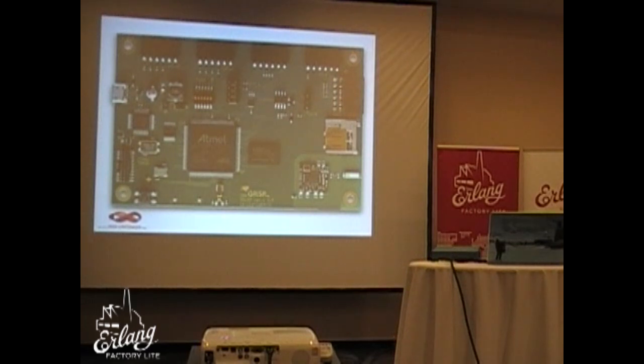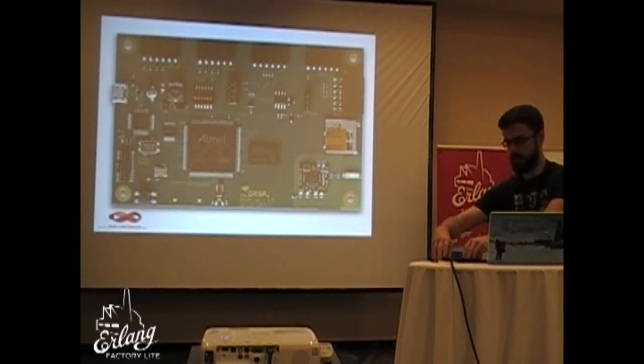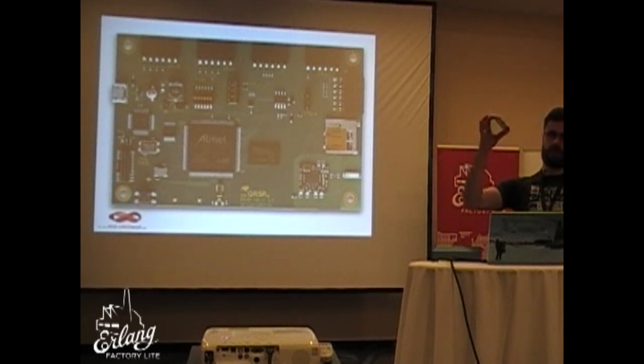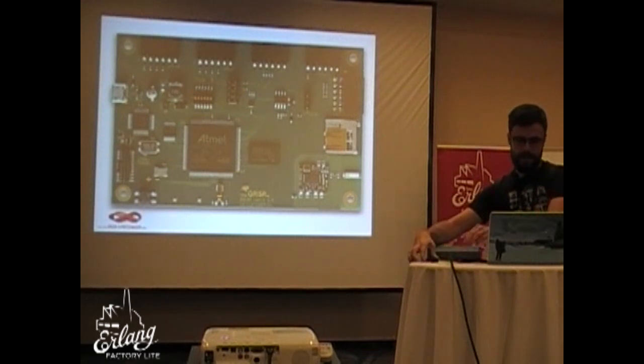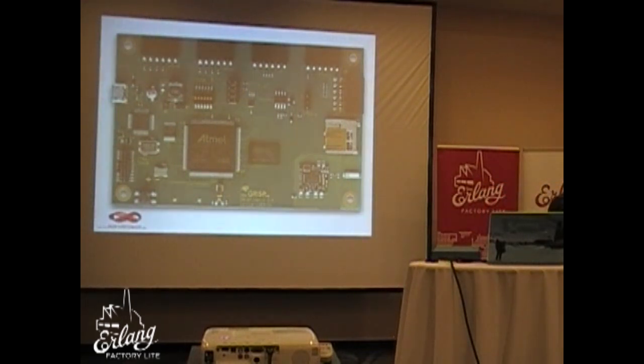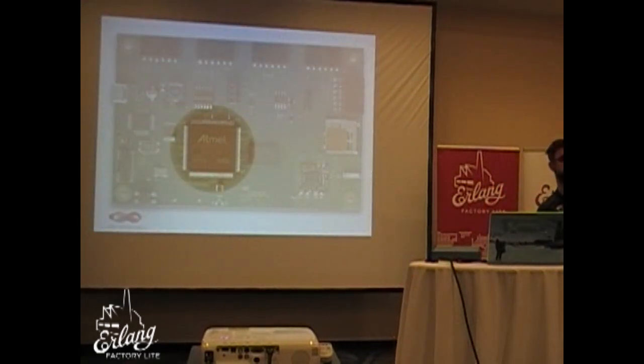So this is the board that we've developed. It's a small hardware board. It's this one here, this size. So it's the current iteration, the current development size. And it has an ARM CPU, a Cortex M7. It's kind of the largest mobile low power ARM that you can get nowadays. 32-bit CPU with some nice stuff on top, like an FPU, a floating point unit, and some other things. I'll go into a bit more details later.